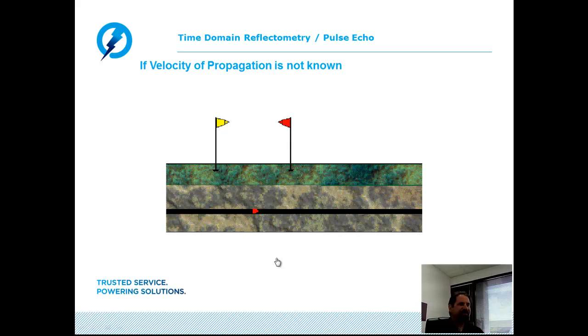So here, even with knowing very little about the cable, not knowing the best velocity value to use, not necessarily knowing true total length, by simply doing bidirectional measurements, I can take 3 miles of cable and reduce it down to maybe a 30-40 foot area to where the true fault is going to reside. And I very quickly took a huge cable down to a very small section that I'll need to probe further in my pinpointing.